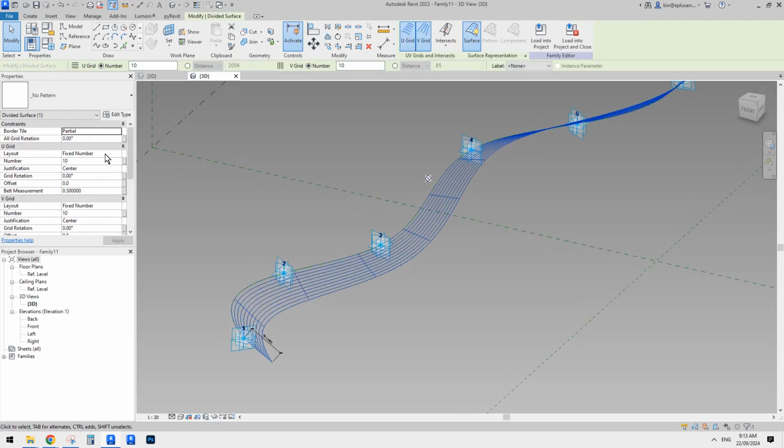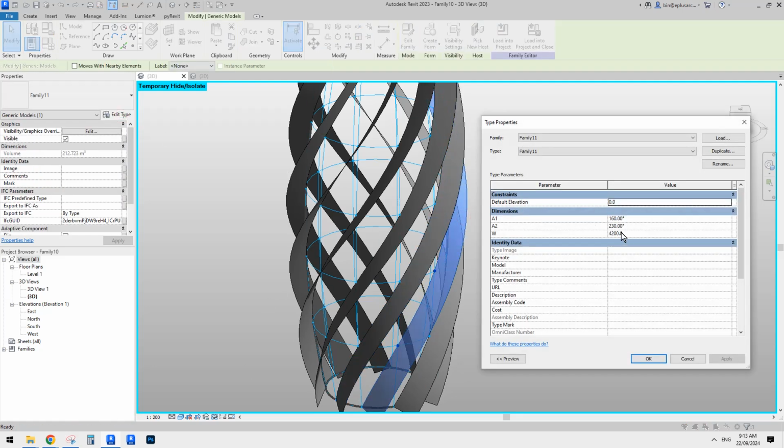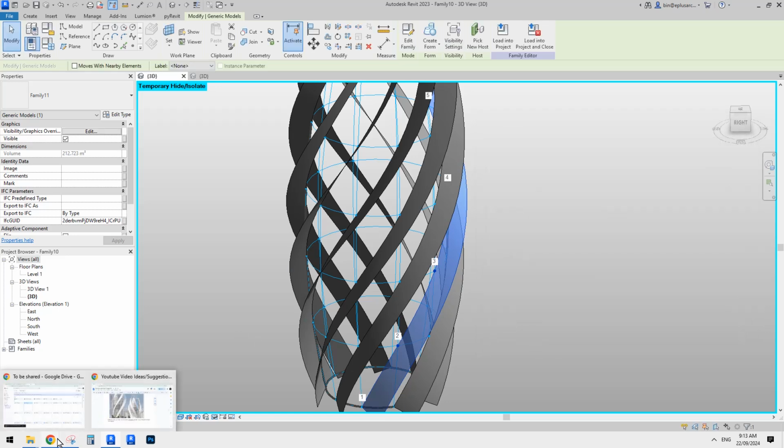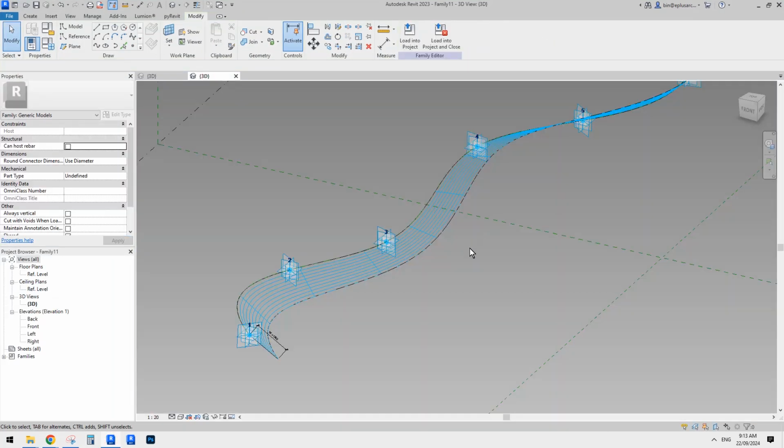So we're going to, what do we use? Which one do we use? Maybe we just use a maximum spacing for this. So in here we have 4 meter, right? 4 meter, and then, hang on, let me just have a look again. 4.2 divided by 3 is 1.4. Okay, 1.4. So maybe we can just make it 1.5 maximum, so it will create 3 panels.